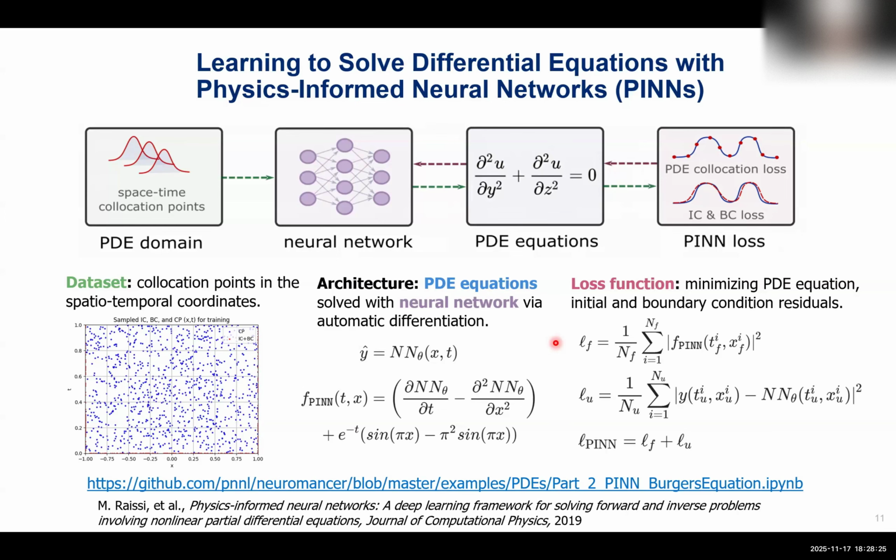Instead of the PDE domain, you first apply a model reduction technique like proper orthogonal decomposition, and then you use the same procedure. There are some approaches that deal with learning the physics in the latent space, and I will go over those later. But I'm not aware of any physics-informed approach in the latent space, because now you have a problem of representing your physics equation in the latent representation, right? So that exactly I'm not aware of.